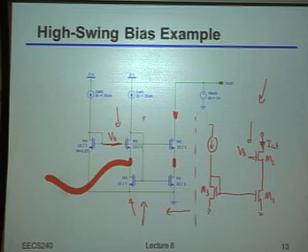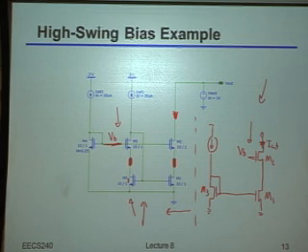Again, in particular for these sort of cascoded current sources, a very classic mistake is to not make the current mirror itself also cascoded. Okay? Because if you don't make it cascoded, the structures are not the same, A, even from just a layout standpoint, but B, more importantly, you're not really controlling the drain voltage bias to be the same on the two sides. And therefore, indeed, you will potentially get very large errors in that current mirroring ratio. Does this make sense to everybody?